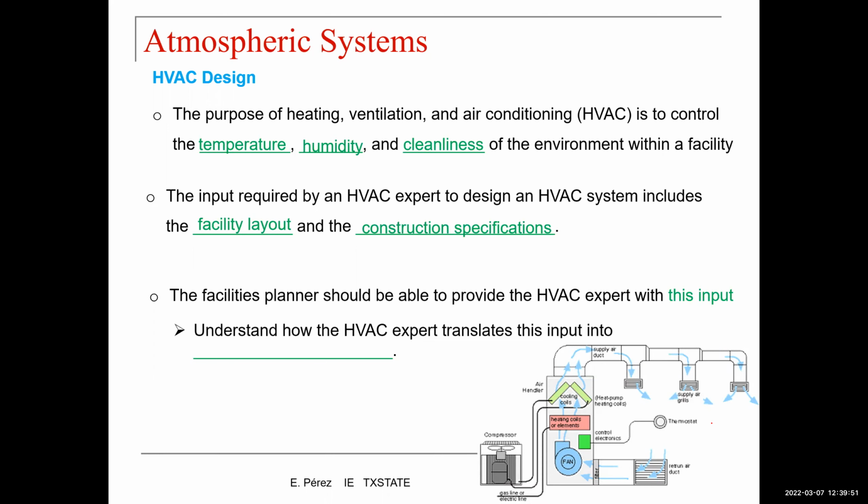Facility layout matters for locating the equipment, and depending on where you locate the equipment, the ducts that I showed you in the previous slide are going to be designed according to the location of the equipment. So the facilities planner should be able to provide the HVAC expert with this input.